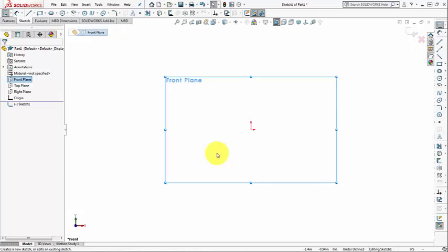This is done by SolidWorks predicting your intended geometry when you sketch. For example, when in edit sketch mode and attempting to create a horizontal or vertical line, simply sketch your line horizontally or vertically on screen, and you will notice a sketch relation will be given in a green indicator.